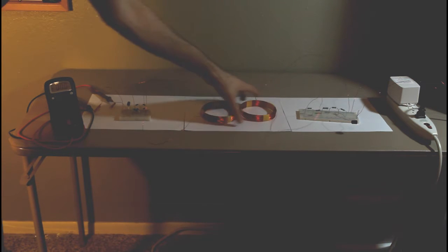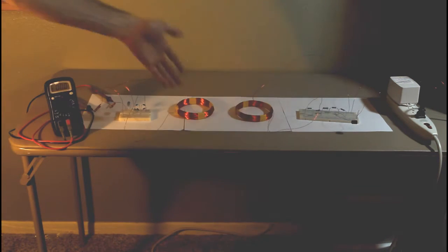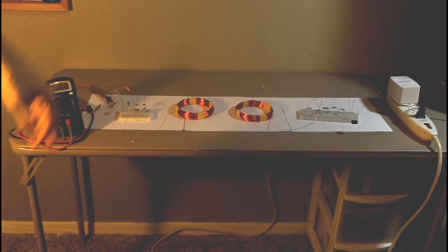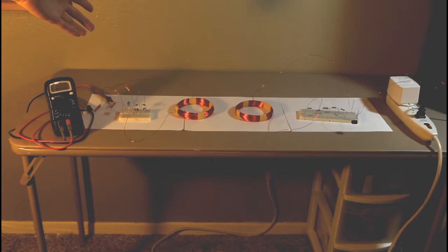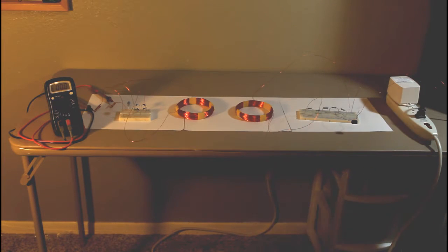Just as the diagram showed earlier, two circuits independent of one another. On the left-hand side, what we call the passive circuit, and on the right side, the active. The one on the left-hand side is the one to be powered through inductance, and the one on the right-hand side is the one hooked up to an AC power supply, basically a transformer supplying approximately 16 AC volts. On the left-hand side, we see a multimeter measuring voltage connected on both sides of the capacitor, and you can see now that it's measuring 0 volts.